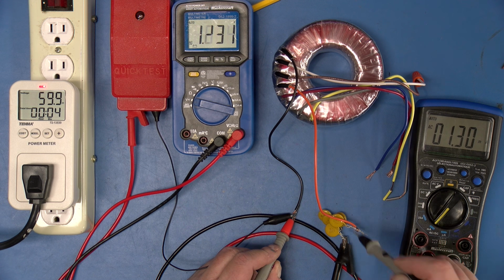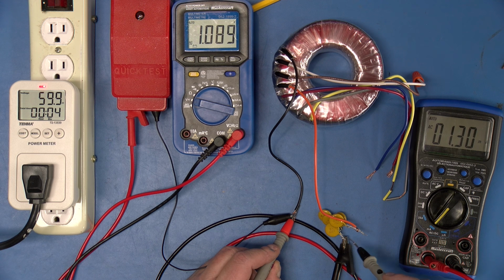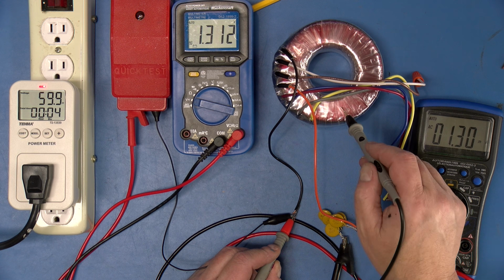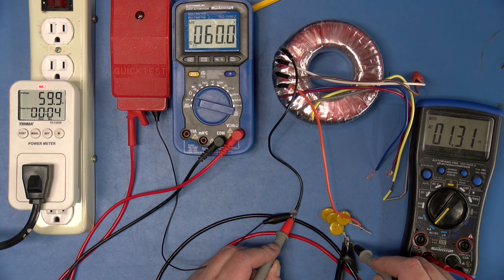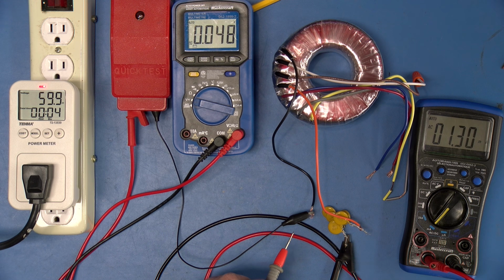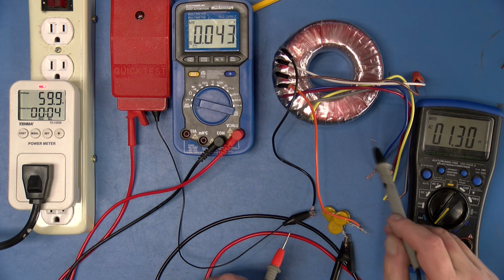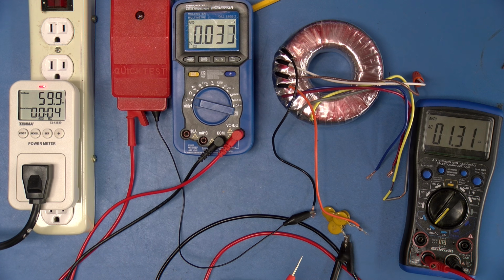And just one more time to confirm, the input voltage across the inductor and capacitor is only 60 volts. There, almost exactly. So that's really quite remarkable. Each one of these two components has more voltage across it than the total input voltage.